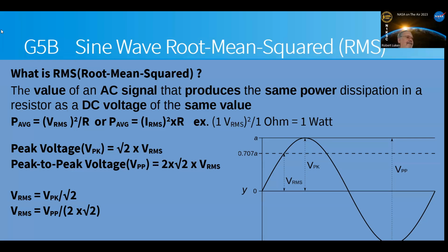Well, contacts will tend to weld on DC because the current's always going one way. Yeah. On AC, it kind of goes back and forth, so it's not as likely to weld the contacts. But I just got a 12-volt DC refrigerator freezer. Okay. And boy, moving from an LP gas one, really nice.